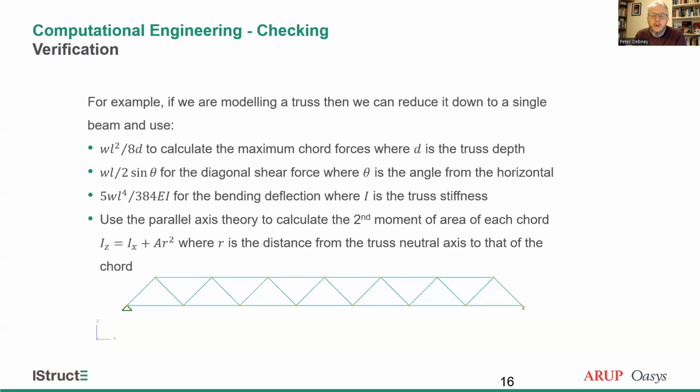And from the bending moment, you can divide by the depth of the truss, D, to give us the maximum forces in the top and bottom boom of that truss. Similarly, the shear force, WL upon 2, then times by sine theta, which is the angle of the end diagonals. That's the shear force in essence.